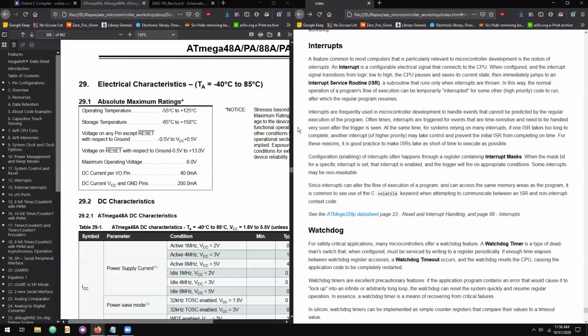And in this case, if you have an interrupt that fires, so you jump into its ISR, if you take too long in that ISR and another interrupt fires, either a different kind of interrupt or the same interrupt even, then you won't be able to complete your operation in time. So you'll either miss information or you'll miss the new interrupt. And both cases are pretty terrible. So you want to generally keep the ISR to a minimum number of statements as possible.